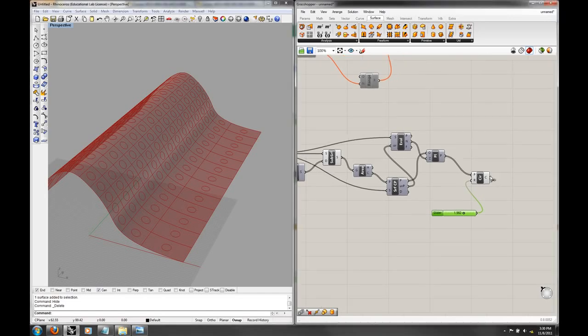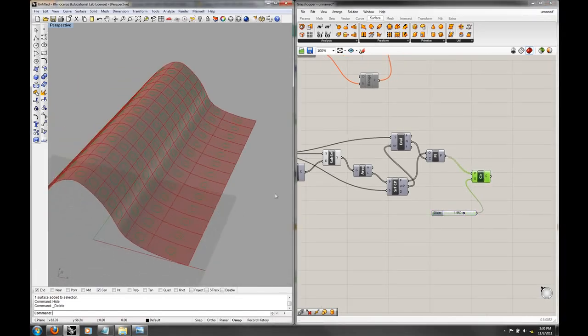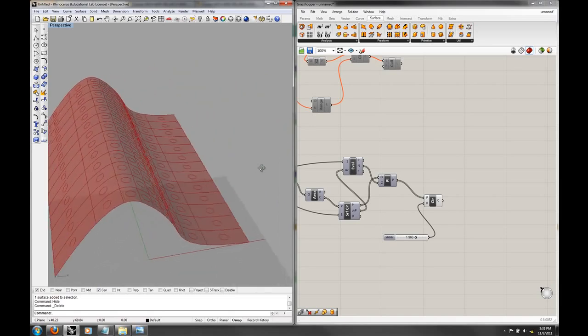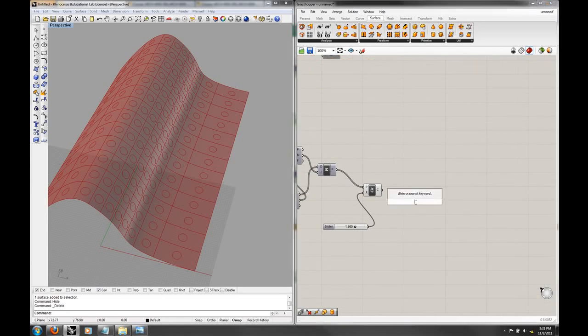You could take these and extrude them. That's kind of what we have been talking about. But you can also punch them out. And I'm going to warn you, this is kind of intensive. Like this might slow your computer down, and it's not something that's going to be actively parametric because it takes so much computation to actually do the operation. So I would work at this level first until you want to begin to punch it out, and then you can do this. You're going to want to do a split surface, or surface split.